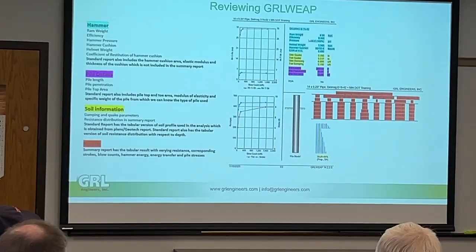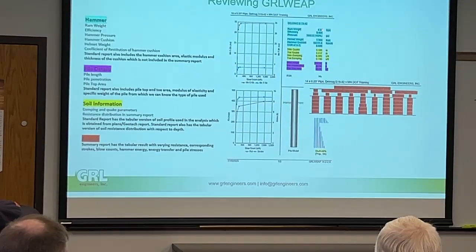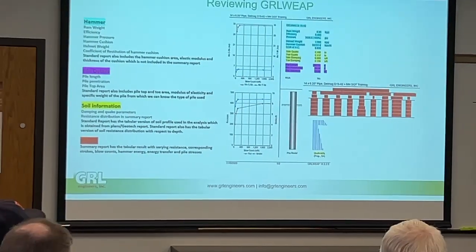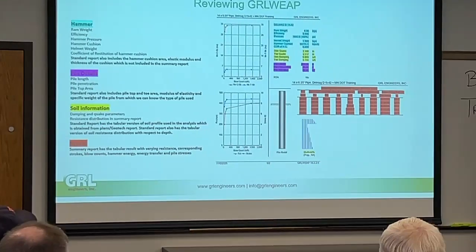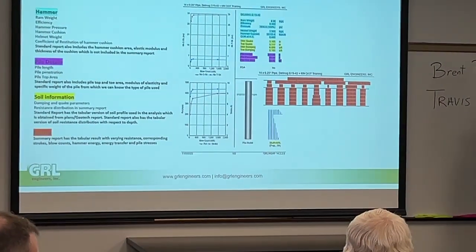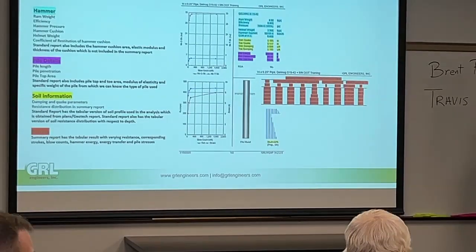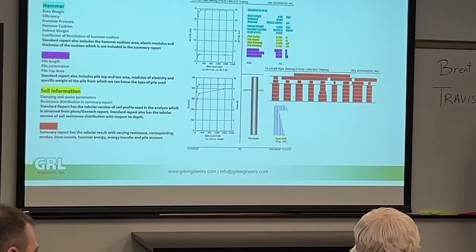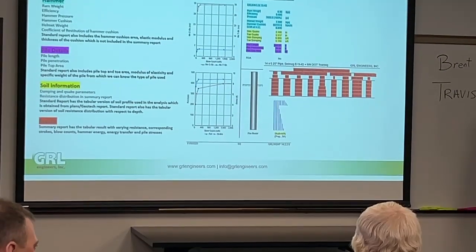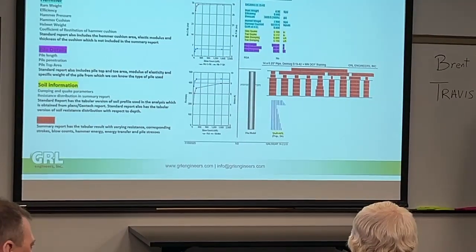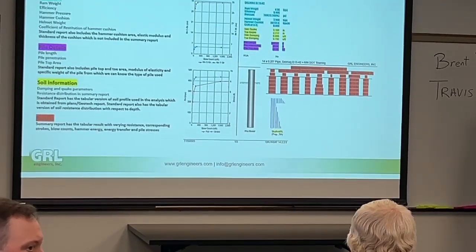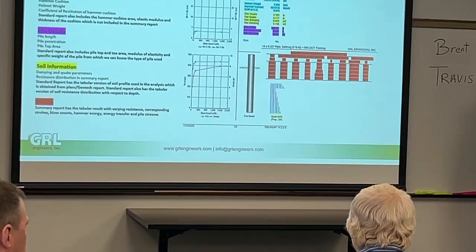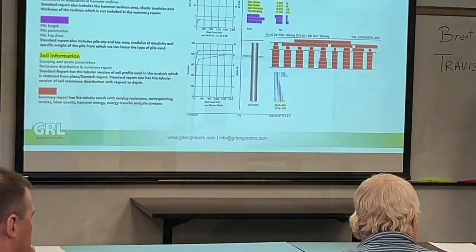The pressure could range from 100% to lower for the fuel settings, but that efficiency should not be touched. The double acting diesels, I think it says that efficiency default is 0.8 as well, but I never see them. We see them for Becker penetration testing occasionally in the west. That's kind of an SPT, but for bouldery, gravelly type soils, where we're looking for strength out of that, but I haven't seen a double acting diesel in a long time either. They still make them apparently, so somebody must use them.